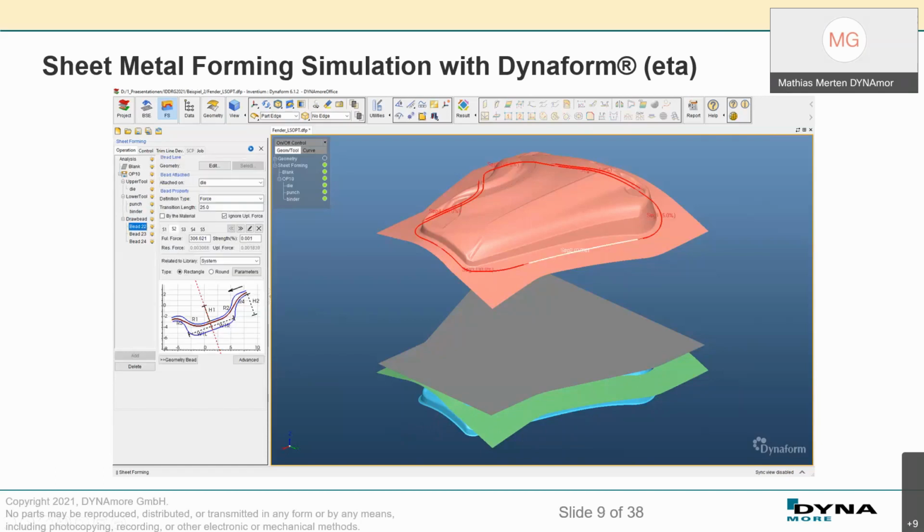In this project or in this process, we also have analytical drawbeads defined. In our case, we needed to adjust them as we changed the material from this project. So they are not the tutorial values we have originally. The analytical drawbeads in LS-DYNA are based on the contact algorithm and are defined with these kind of lines where we have so-called force factors.